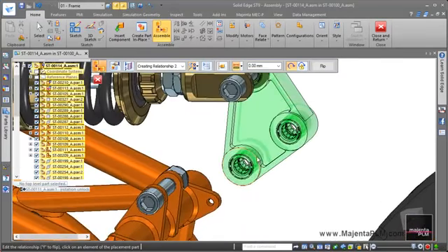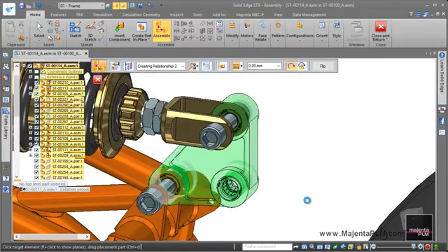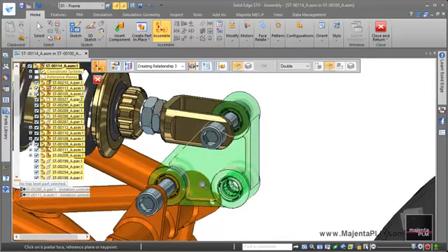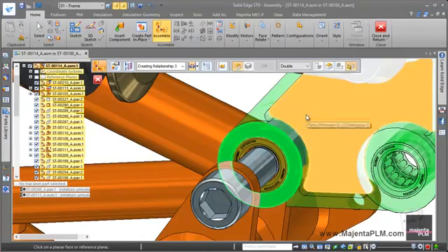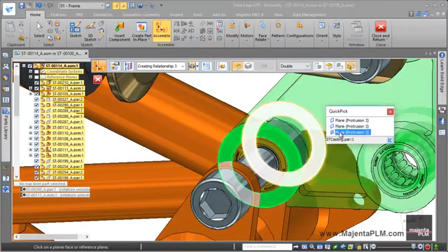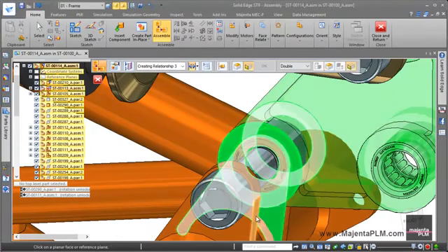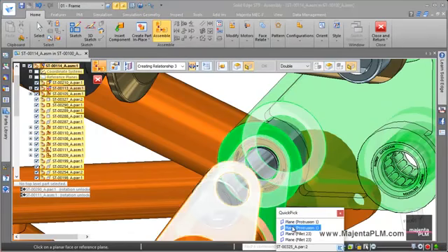Then repeat the same process for the frame. We need this to be centered, so to save extra work involved with measuring gap distances, we'll use a special relationship. Identify the extreme faces, and then Solid Edge centers the part for us.